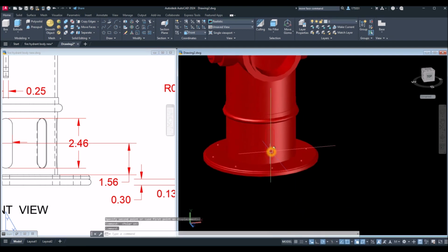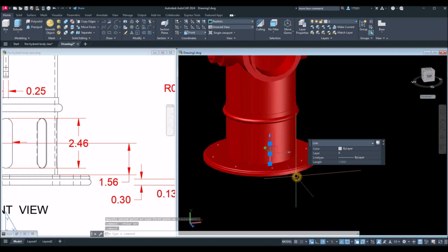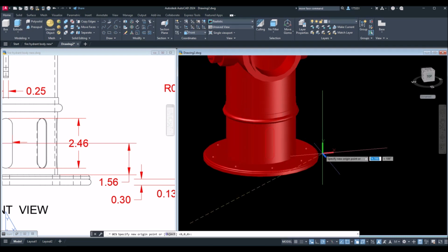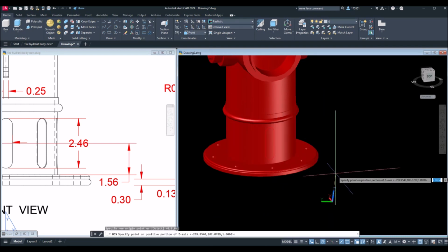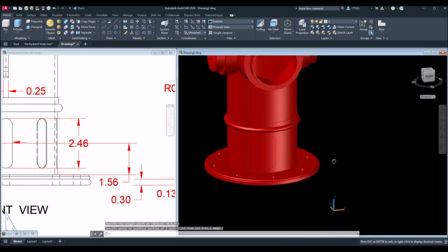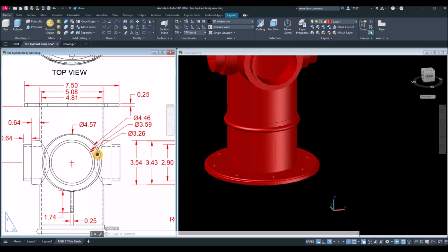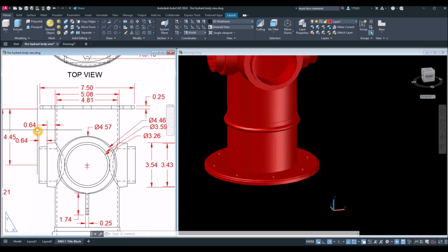Alright. I'm just gonna delete that line. Now I'm gonna apply array polar, but before doing that, change the direction of your z-axis vector. Click anywhere on the screen and move it upward. I'm gonna extrude this one first. Maybe less than the thickness of the barrel, otherwise we're gonna poke a hole through the barrel.